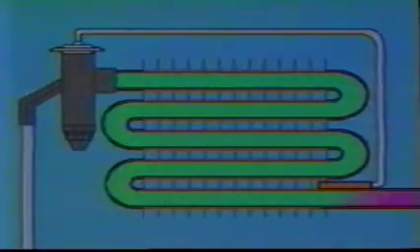The first question we must answer in setting any thermostatic expansion valve is, what superheat do I want to maintain at the evaporator outlet? That question might at first seem easy. One of the reasons we use superheat is to be sure all liquid has evaporated and superheating of the refrigerant vapor has started. That suggests a very low superheat of 1 or 2 degrees would do the job. True, this low level of superheat would give us very high efficiency for our evaporator because liquid is more efficient than vapor in absorbing heat.